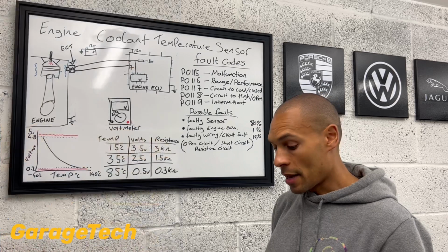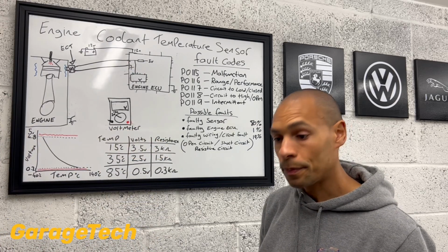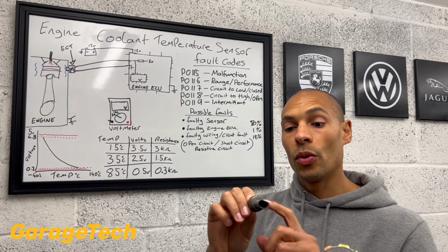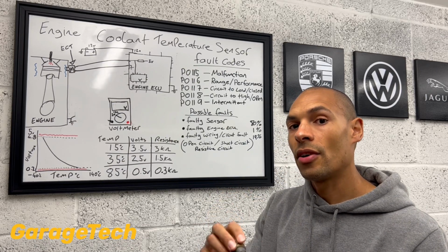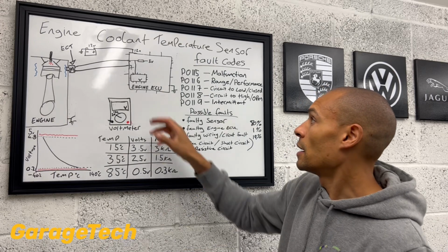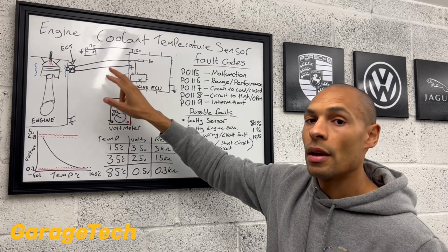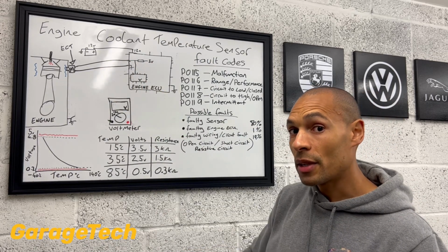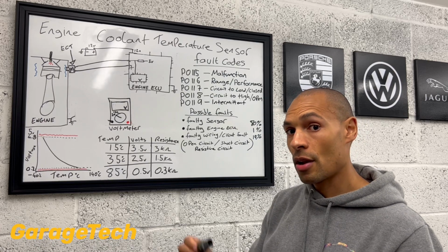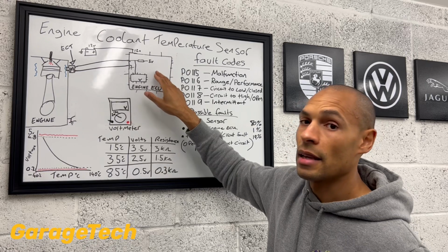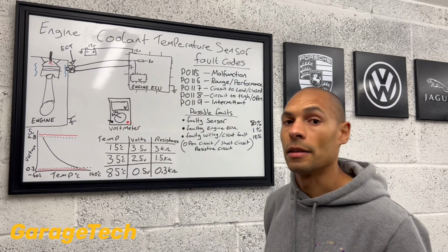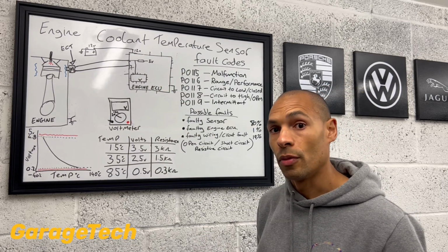So again, sometimes a bit of a common fault. The temperature sensors will leak coolant that can go up into the actual plug, then it can get corroded inside, then obviously the electricity can't pass through the circuit correctly, and particularly with this type of circuit where it's based on resistance measurements, that's really going to affect the reading that the engine ECU is taking. So that could be a possible cause there.